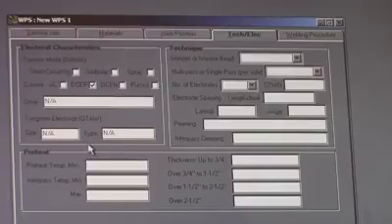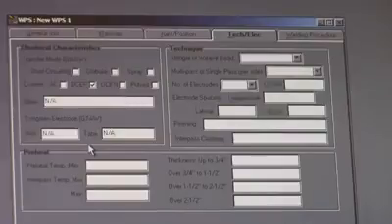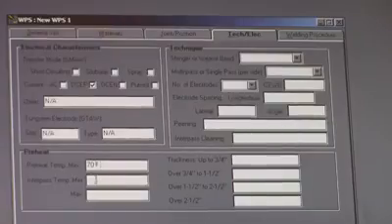Preheat minimum temperature. I used to put down ambient, so that'd be like 70 degrees. And I sent it to a couple customers, and they said, I don't want ambient, I want an exact degree. So I always put in 70 degrees Fahrenheit. Interpass temperature again, 70 degrees Fahrenheit, and a max of 250 degrees Fahrenheit. The interpass does matter because you're going to be doing multiple passes on this. You're not going to be able to fill that joint up with one pass.